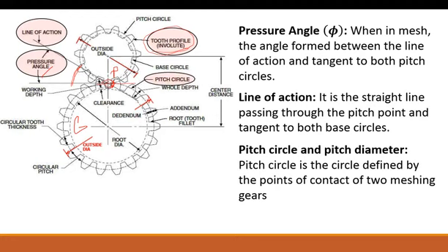Now, there's a lot more to this. There's an addendum, which is the top of the gear. There's a dedendum, which is the bottom of the gear. There's the root and the fillet. All these things are important, and they are going to come up in a lot of our future calculations, and they play a major part in gear design. So when you design a gearing system, these are the things that you're definitely going to end up touching on, as well as some of the others, but these seem to insinuate themselves all the way through gear design.